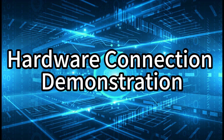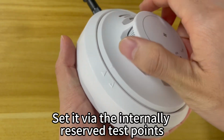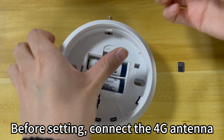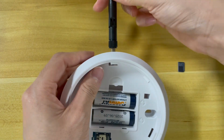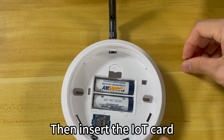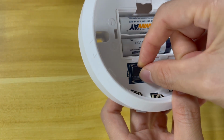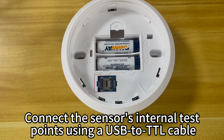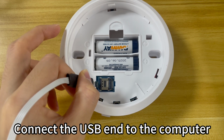Hardware connection demonstration. To configure sensor parameters, first open the sensor. Set it via the internally reserved test points. Before setting, connect the 4G antenna. Then insert the IoT card. Connect the sensor's internal test points using a USB to TTL cable. Ensure the wiring sequence is correct. Connect the USB end to the computer.